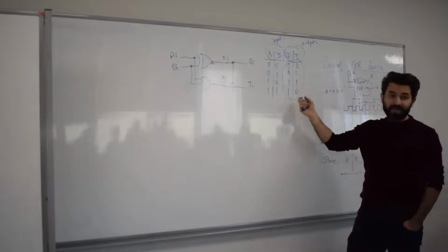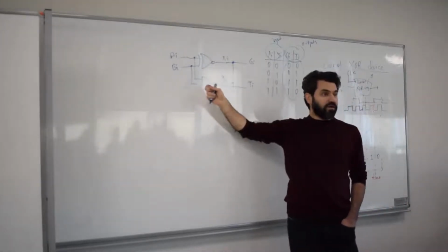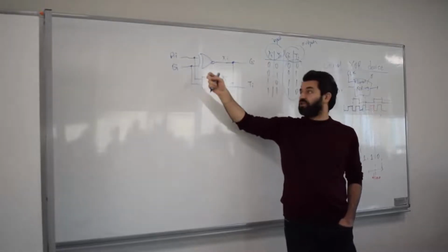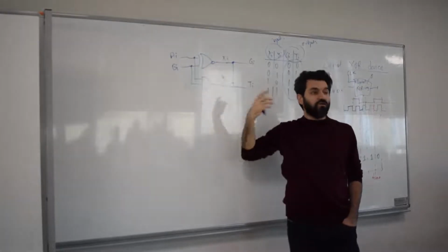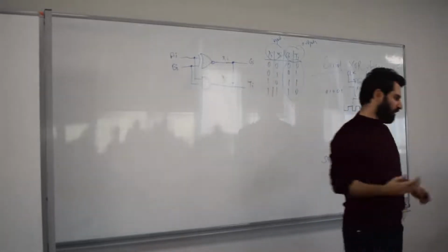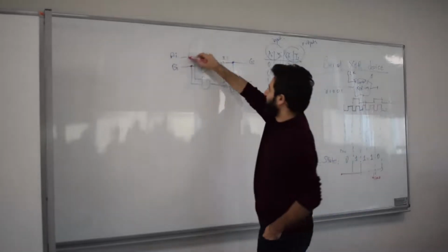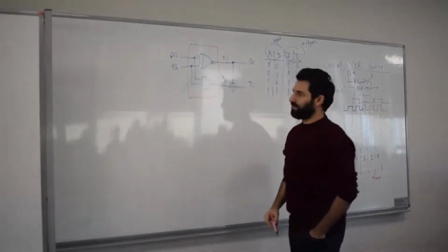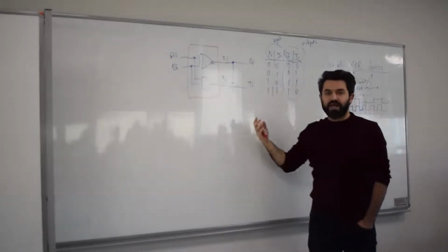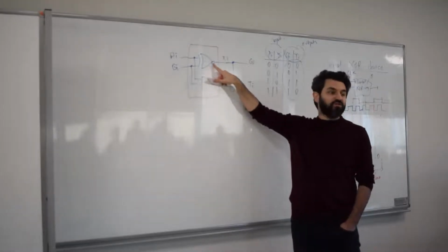But you can't say the same for this circuit because there are irreversible gates, such as XNOR, which is an irreversible gate. If you do not believe me, let us draw the truth table for this particular component. I would tend to say it's a half adder, but it's not, because this is not an XOR, this is an XNOR gate.